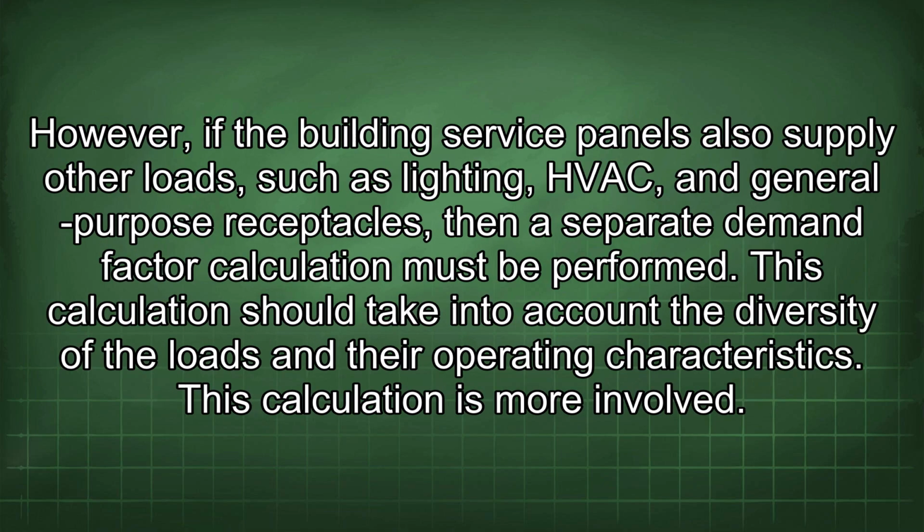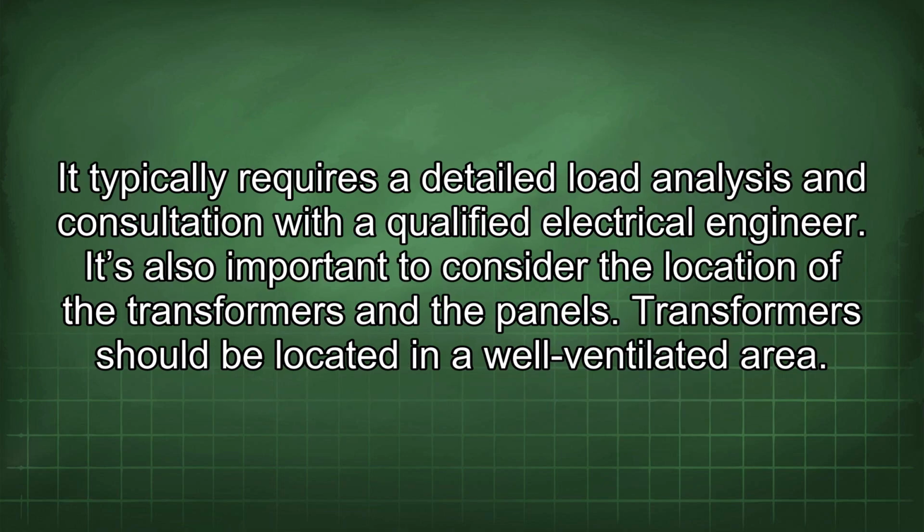However, if the building service panels also supply other loads such as lighting, HVAC, and general purpose receptacles, then a separate demand factor calculation must be performed. This calculation should take into account the diversity of the loads and their operating characteristics. This calculation is more involved. It typically requires a detailed load analysis and consultation with a qualified electrical engineer.